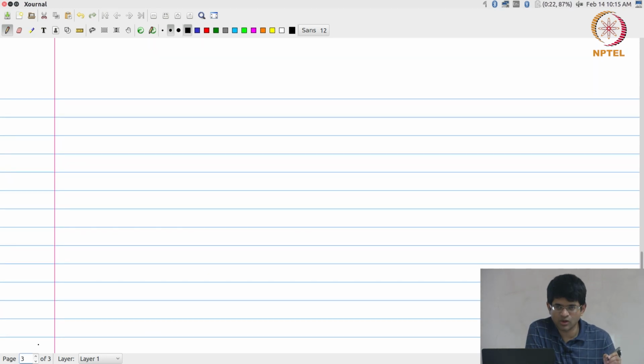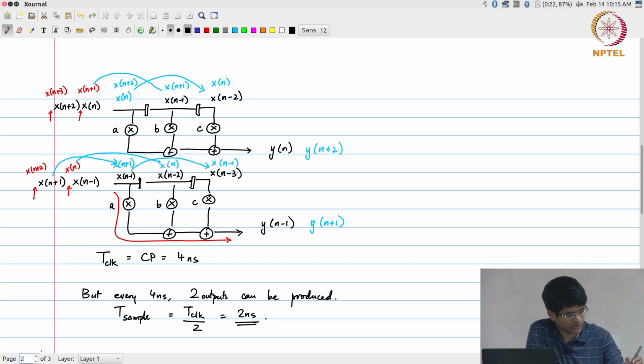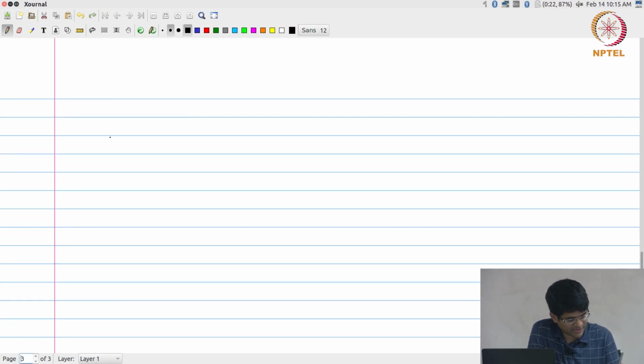The twist that we can observe as far as parallelism is concerned is, if you go back and look at this diagram over here, you will notice that, for example, this x of n minus 1 is occurring in two places. Similarly, x of n minus 2 is occurring in two places, right, and I am effectively having to put two registers over there and generate those data, right, separately. What if I try and sort of combine that? What it would look like is something like this.